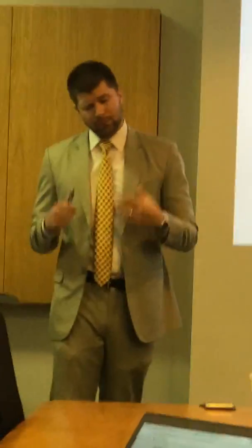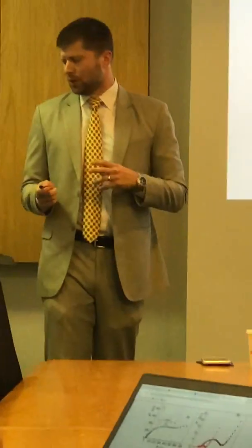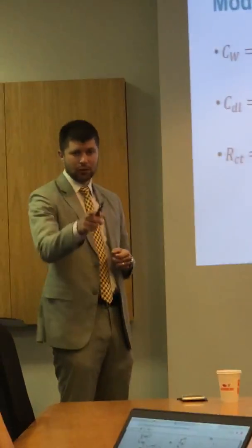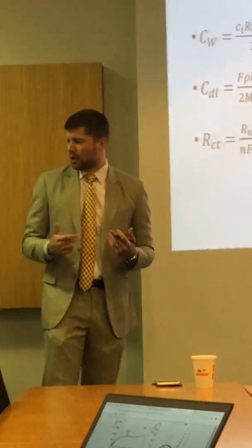So I ended up pouring through the literature, doing a bunch of derivations myself, and finding equations I could use to represent the various elements that you would see in a traditional Randles ECM as a function of all those constituent parameters that I had access to that went into designing that cell.